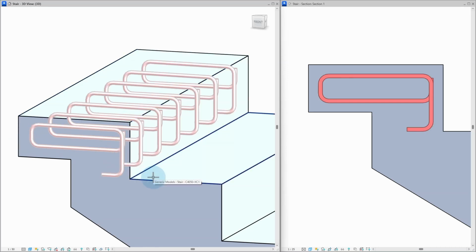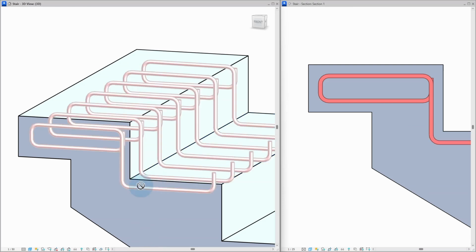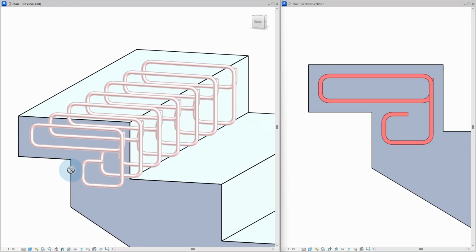The bottom segment does not follow the cover. I'll simply select a parallel face for now. Notice that the exact spot where I click on a face determines the direction the rebar turns. But there's no need to worry too much about precision. For internal segments, the command automatically corrects mistakes to produce a valid shape. This is more strict for the end segments.